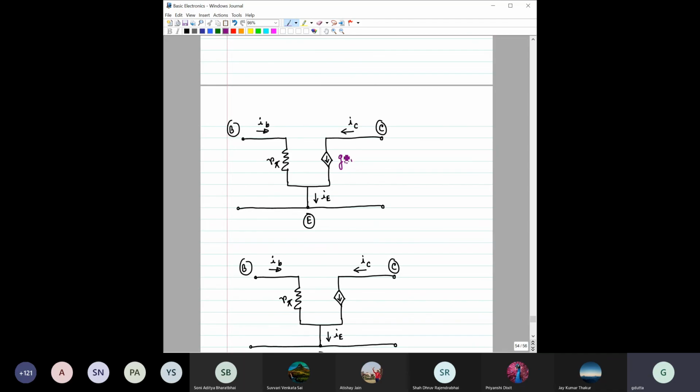So you have resistance and conductance together. In the H parameter case, you will also see voltage gain and current gain along with the resistances and conductances, so everything is mixed, hence it is called hybrid. In the Z parameter case, everything is represented by impedance, and in the admittance parameter case, everything is represented by admittance.